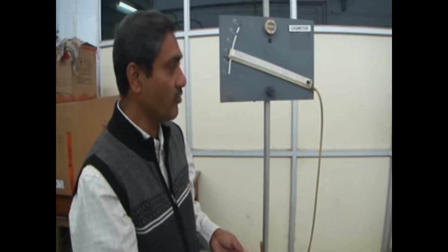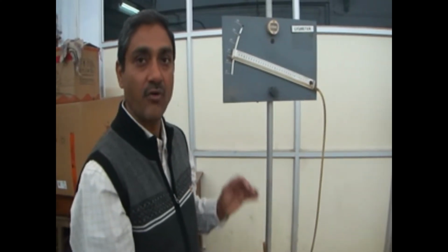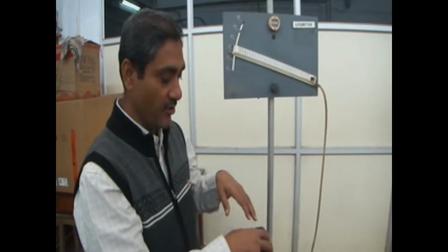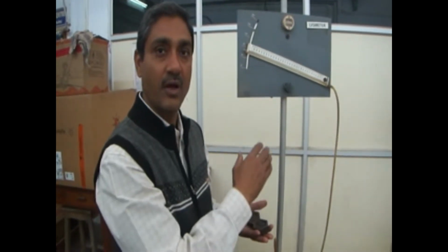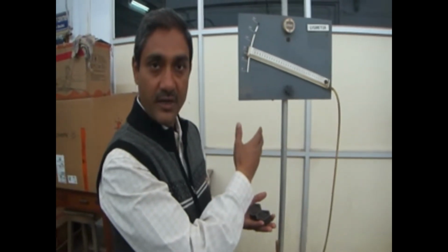So we need to find out the characteristics of addition of water, or addition of this weight, and removal of the weights, or removal of the soil moisture from the actual field. If we develop these characteristics as a calibration condition, then in the actual field, if we have the weight or the hydraulic head or the final weight, we can find out the soil moisture condition in the field.